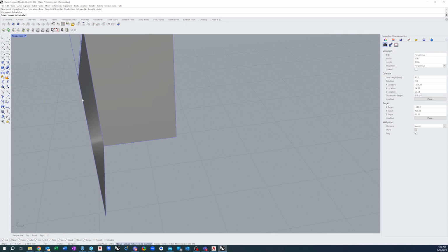I'm going to click my curve. Now you'll see my return leg's not going in the right direction, so I'm going to hit D for direction, which is also up here. It's going to ask me what direction to go, and I want it to go in this direction. So now I've got my leg, and for my first return leg, it's set to 0.986 inches.